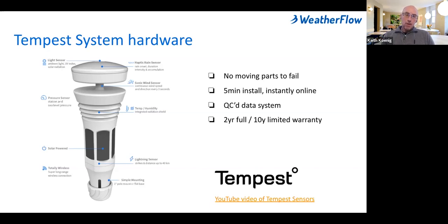It was very clear that we needed to account for solar radiation and overheating causing a skew in the temperature. And so we developed mathematical formulations and onboard algorithms that look at the temperature, the solar radiation, the wind, and when you know the thermal dynamics, you can apply a coefficient and normalize the temperature to account for the influence of solar radiation, giving you a very accurate ambient temperature reading, even though it's in the full sun.